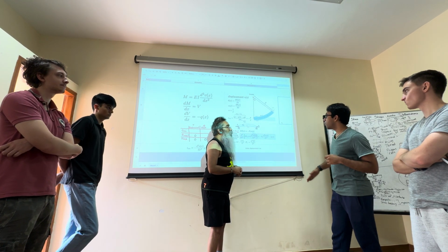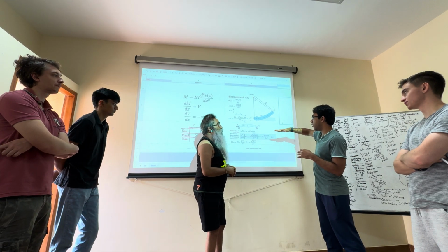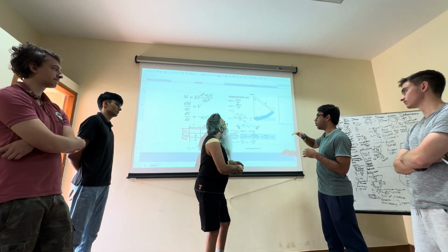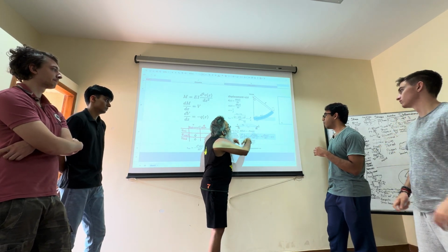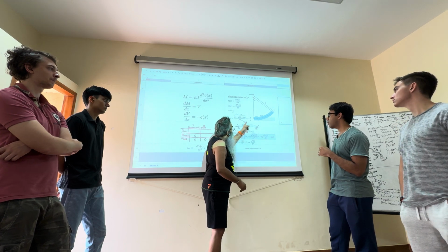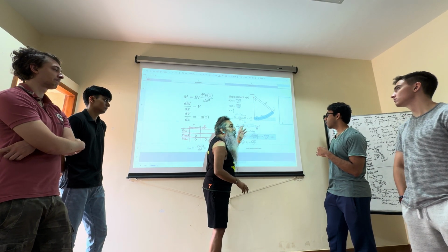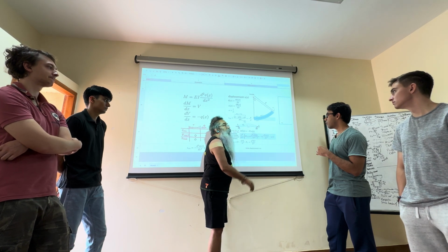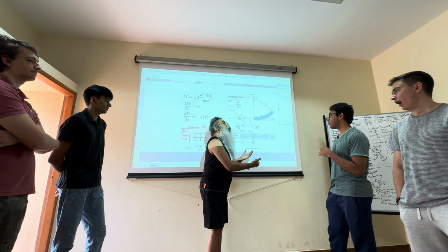So I guess in this case, we're not including any eccentric loading because it's acting directly on the middle. Right, ideally speaking, that's how we get it for the model. But that's what happens in reality. The reason it bends, you will not actually be applying any load in that particular direction. It just so happens because of the imperfections that are there in the actual system, which is not idealized.